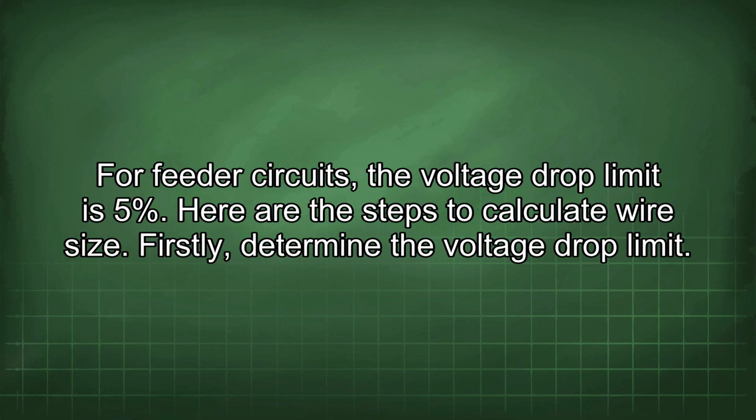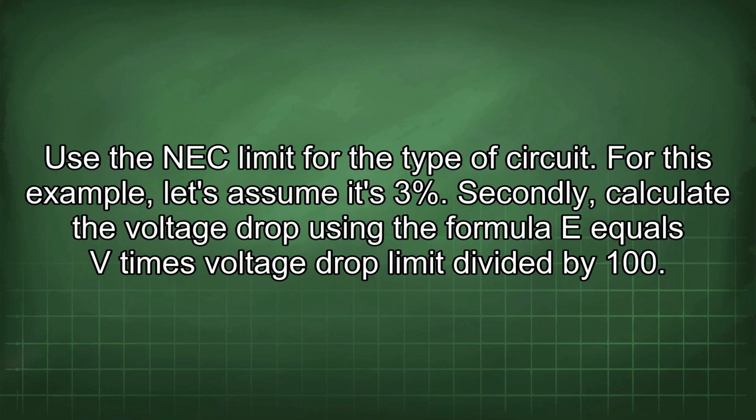Here are the steps to calculate wire size. Firstly, determine the voltage drop limit. Use the NEC limit for the type of circuit. For this example, let's assume it's 3%.